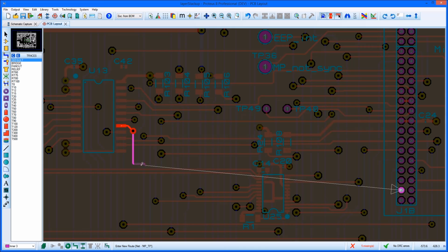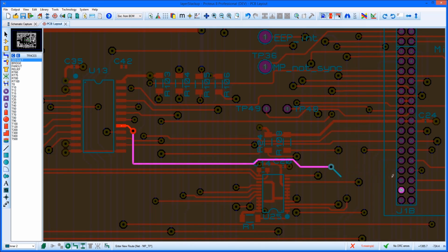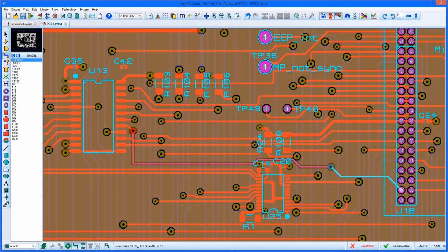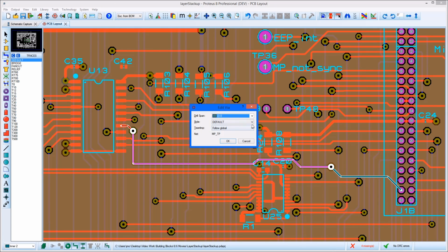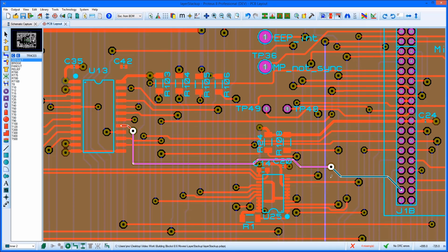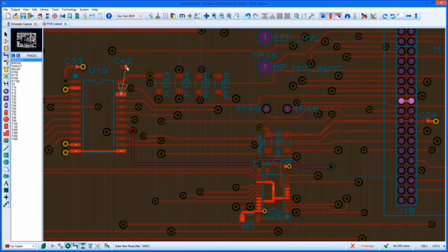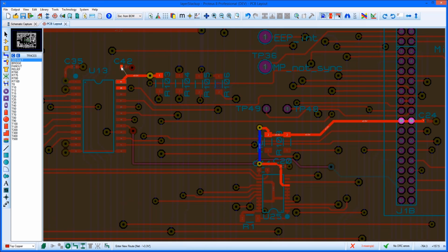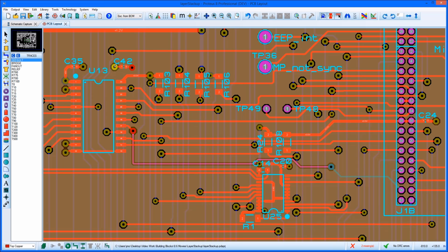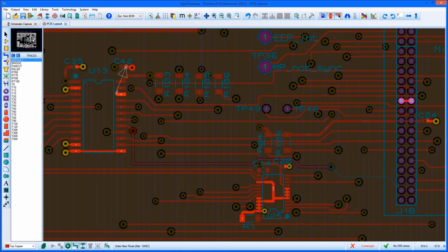The main place Proteus uses Stackup information is when routing the board. For example, in our Stackup, if a route is placed between inner 2 and inner 3, the via used will be a buried via. If we route from a power pin and double-click to place a via, Proteus will first check if there is a plane layer underneath or above the mouse position. If there is, it will automatically compare nets, and if they match, it will complete the connection for us.